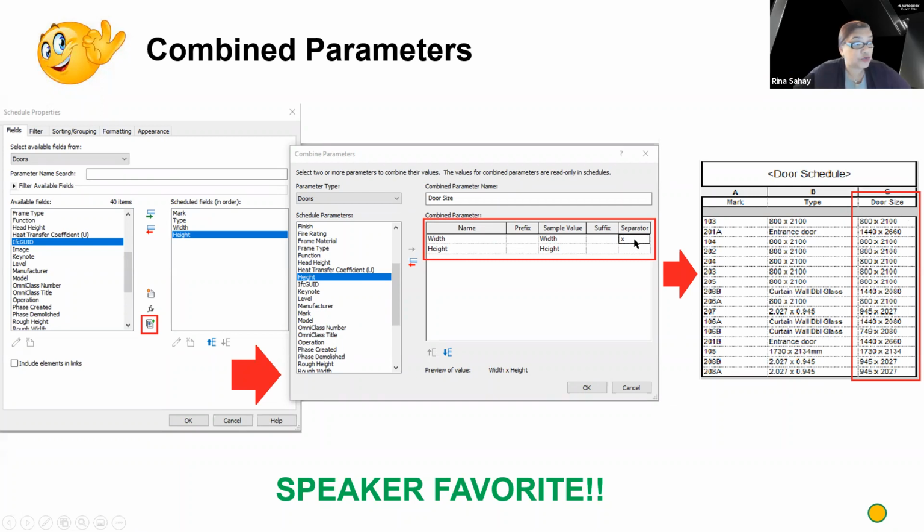Secret tip for you. You don't have to use a separator. Supposing you are in a situation where you're trying to combine parameter A and parameter B, and it may be that some components would have both parameters, some would have A, some would have B. In that case, for the instances which only have, let us say, parameter A, the separator is going to show up. You don't want that to happen. Don't use a separator. In that case, take the separator and put it in as a prefix or a suffix. If either parameter A or B is not present, then the prefix or the suffix will not show up. One less thing for you to worry about, right?